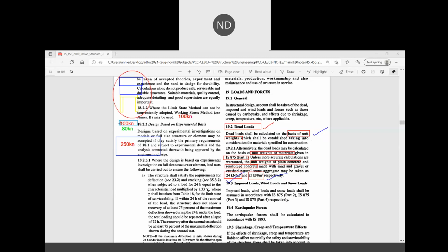And further 20 more kilonewton of load, it can carry extra load, so no problem to us. So we can use this beam here, right? As compared to this, what is the disadvantage if we use this over this beam? The disadvantage is that the structural weight of this particular member is going to increase, and as this load increases when we place it here, the entire structural load will increase, right?